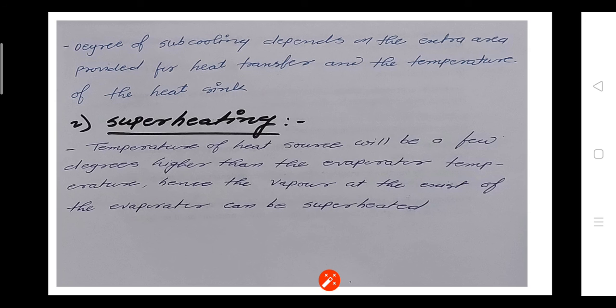Now how much the COP is increased, and whatever area you are providing, whatever cost is required for that area, that will be feasible for the performance of the VCR cycle. Okay, you have to check that.